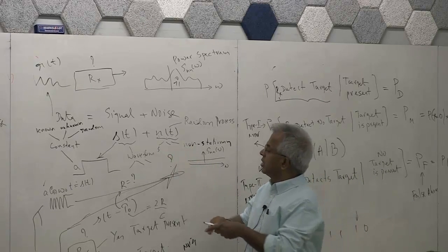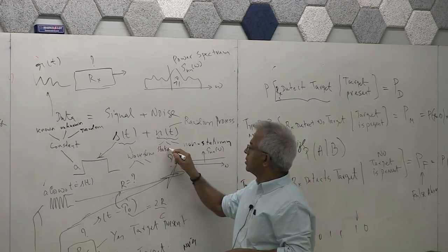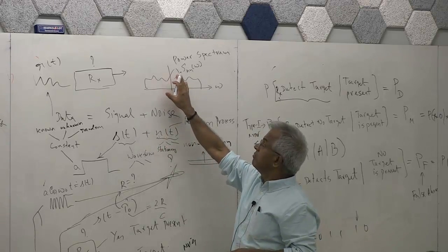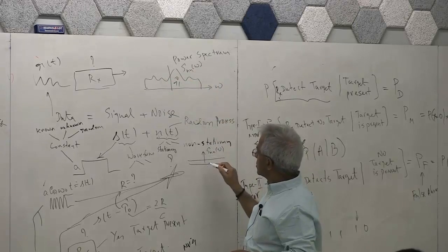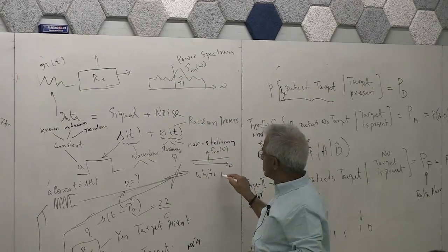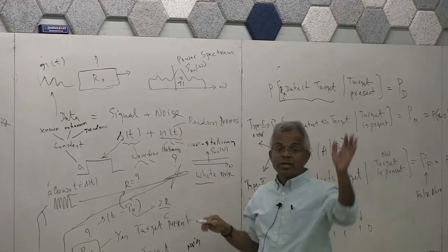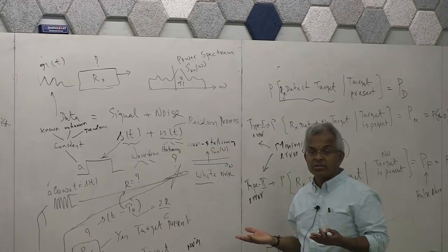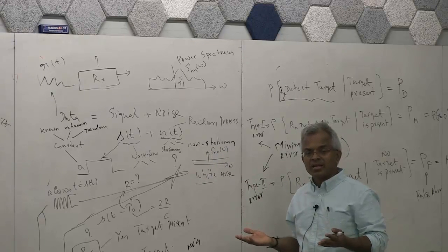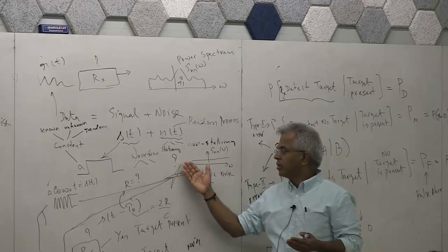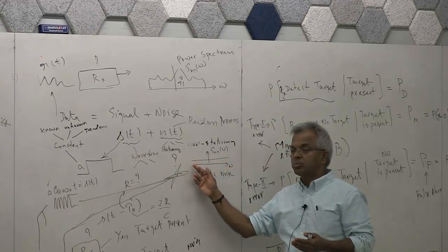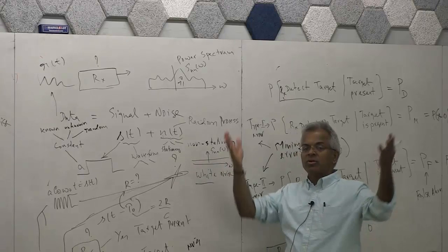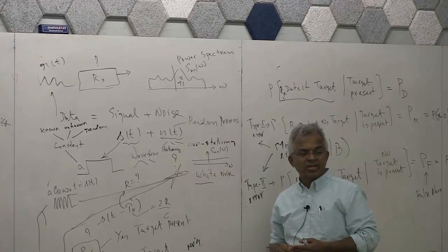Okay, so you have stationary noise and non-stationary noise. If it is stationary, you can have various power spectra. As I said, one popular power spectrum is white noise. You might have heard the term. That means, like white light, all the frequency components are present in the noise. Of course, it's unrealistic, because if all the power is present from minus infinity to plus infinity, the total power, which is the integration of all this, will blow up. So that's an idealization. It's like a delta function.